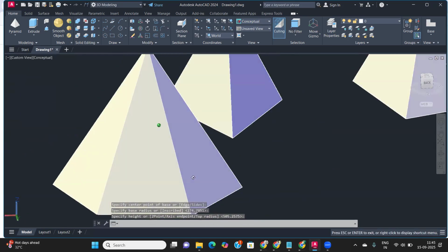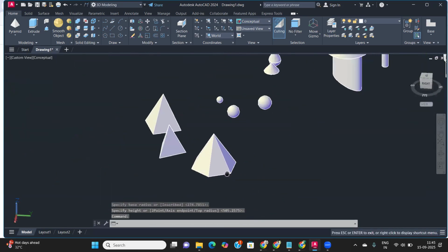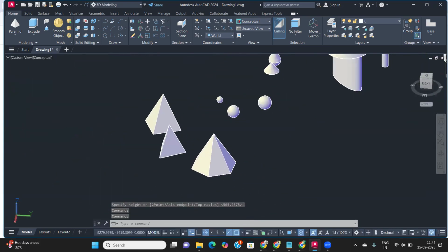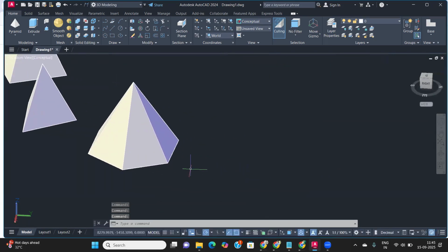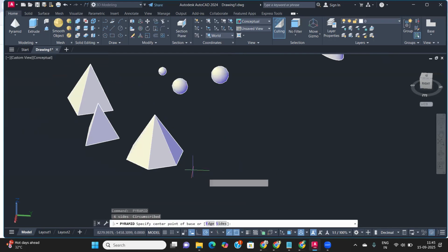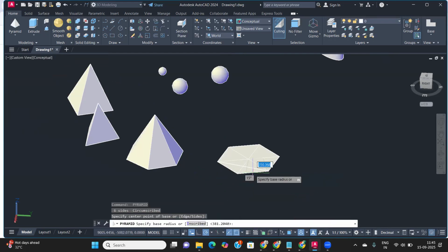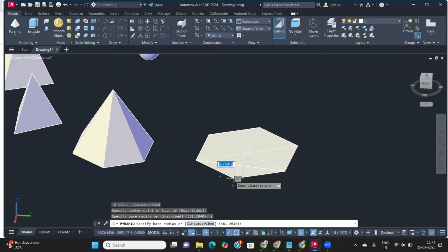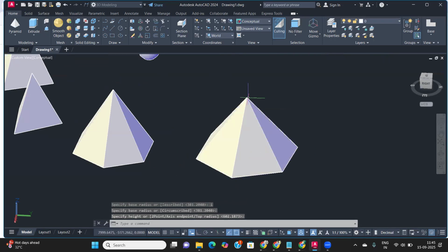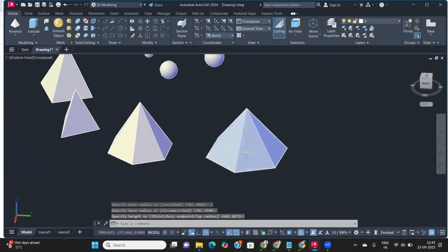Okay, you can take any size, and whatever your base is, it is your polygon format. Okay, easily you can take the polygon, and then after you can take the height and then make this type. Okay, come to this part. If you want to check the size, then in this size we have by default the portion of circumscribe about the circle. If you need the inscribe of the circle, so I enter I for this part, and then we keep here. Okay? Inscribe the circle part.